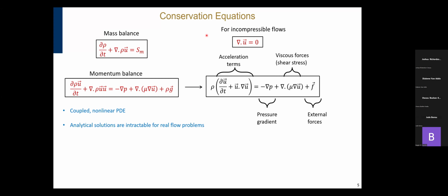Okay. So to answer your question, in crystallization, you are looking at maybe a different set of equations, but you also have the transport equations out there. So you could use CFD to come up with a good mixing strategy that would prevent supersaturation gradients, right? In your crystallizer. And then based on that, you can operate your crystallization process.